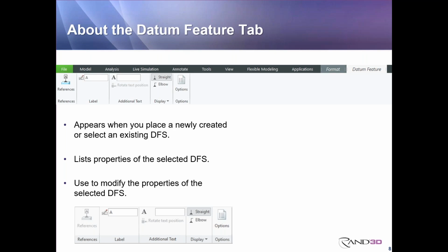That option command allows you to control the position of the model-driven datum feature symbol shown in the drawing. So you have a dependencies option, which is available only in drawing mode, that will allow you to determine the position of the model-driven datum feature symbol. A couple of options: placement position, where you can specify the position of the selected datum feature symbol as driven by model, or attachment, where you can specify the attachment point of the selected datum feature symbol as references driven by model, or the other option is attach points driven by model.